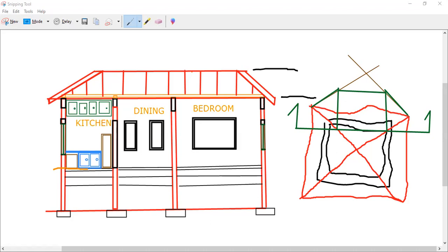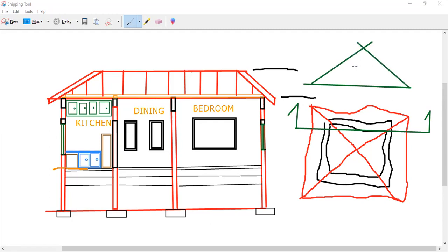So this is basically how it would look. Probably I should draw it at a different location, or you could also draw it this way. You could draw a horizontal line here, which is your start point. Ideally, draw this line the length of this. Then draw a 30-degree angle there. This would be 30 degrees on the inner angle.